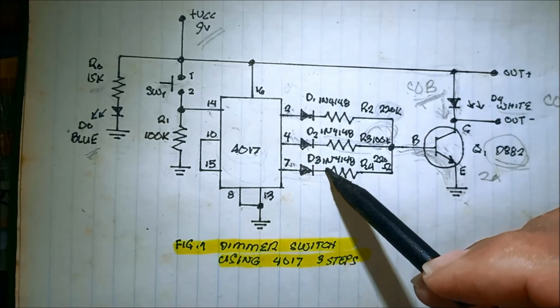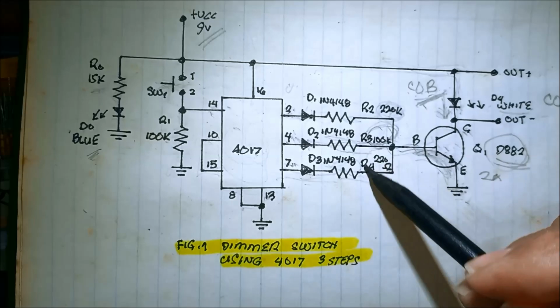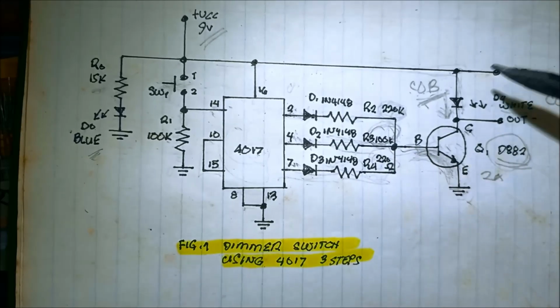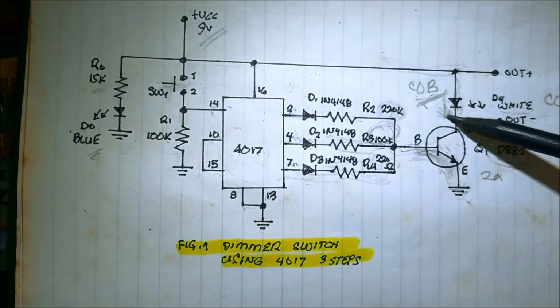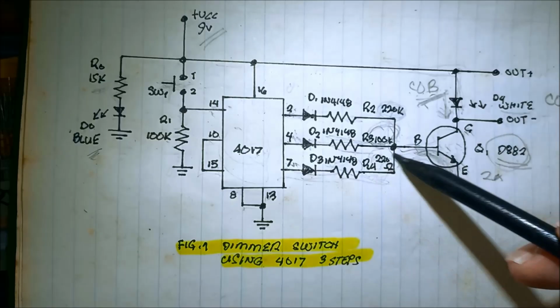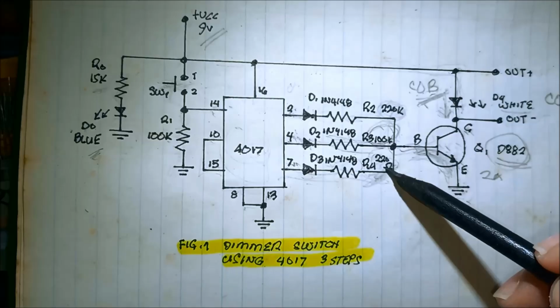Current flows into the switching diode also to the 220 ohm resistor. So less resistance, switching on the transistor again, resulting in a brighter LED, because the biasing resistor of 220 ohms is less.